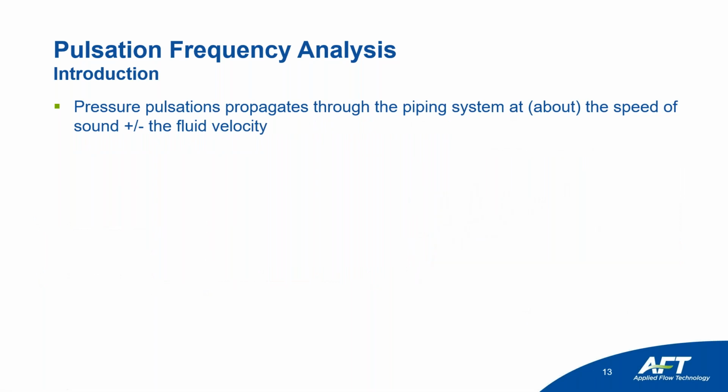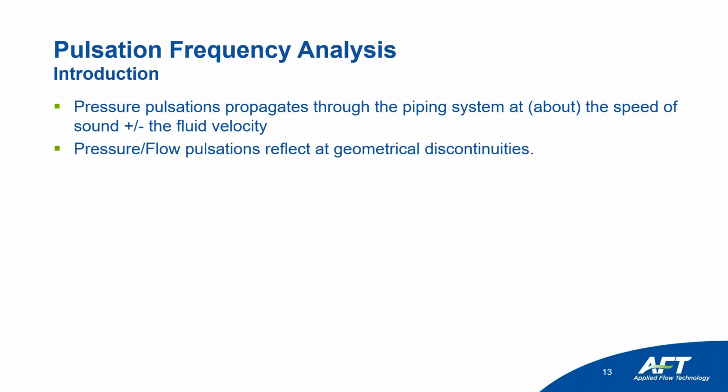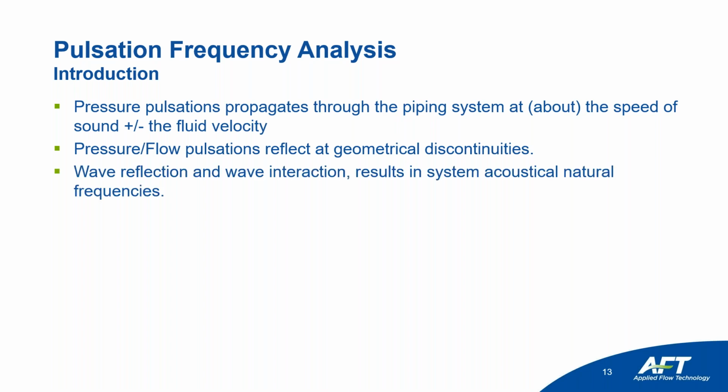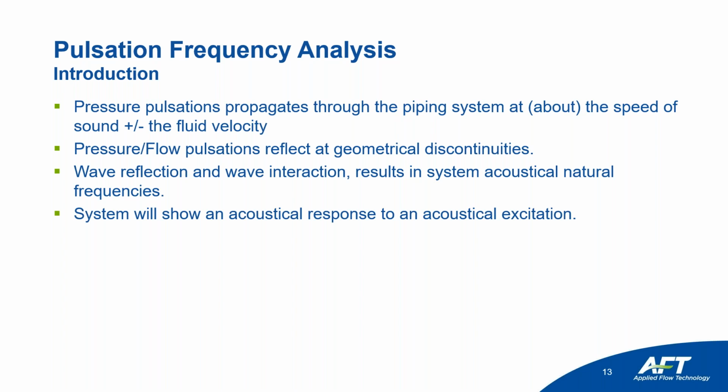Pressure changes travel at a speed that's a combination of the sonic velocity and the bulk velocity. The pulses can reflect at bends, valves, dead ends, or other boundary conditions in the system. Reflected waves interact with other waves in the system, which is the basis for why systems have natural frequencies. An acoustic input can provoke an acoustic response.